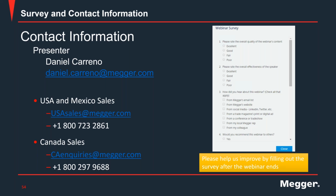The other thing that you want to make sure of is that the vector group is selected right. Selecting a wrong vector group would result in an obvious error, and the ratio errors that you would get would be much higher than 0.5%. But these are the two main factors you would want to look into to avoid operator error.